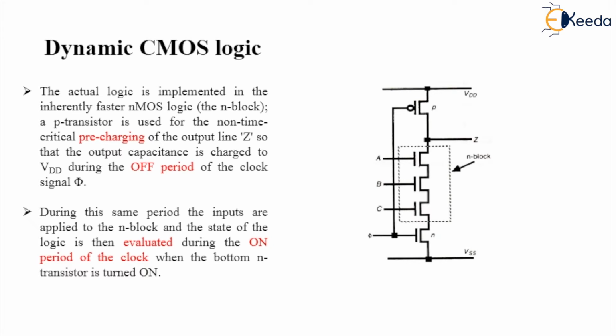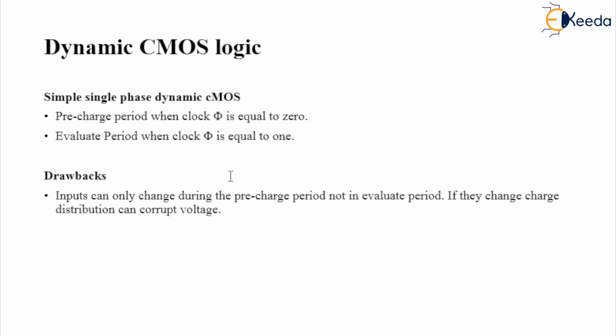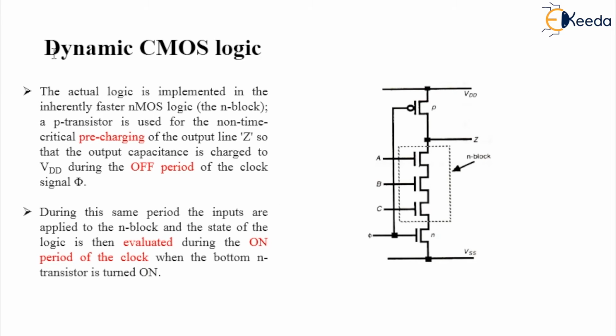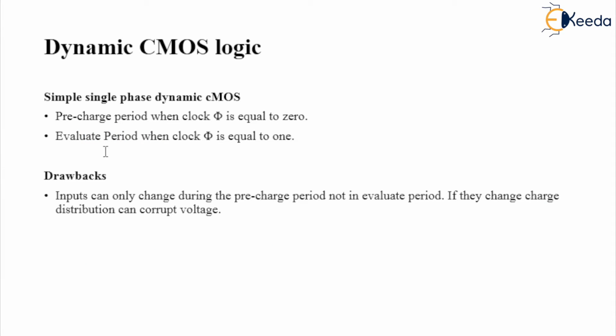So that has been written in the next slide. This is all about simple single phase dynamic CMOS logic. I have simply written 2 points here, which is the description of this total circuit. The pre-charge period is when clock pi is equal to 0, and the evaluation period is when pi is equal to 1.